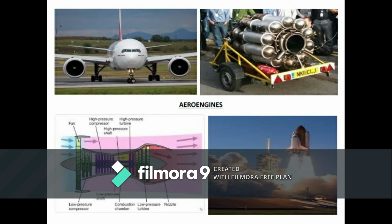The difference between ramjet and scramjet engines is that in a ramjet engine the combustion takes place at subsonic speed. That means the supersonic speed of air is further reduced in the air intake, and that reduced speed air is taken to the combustion chamber, and there combustion takes place. Again after expansion it becomes supersonic.